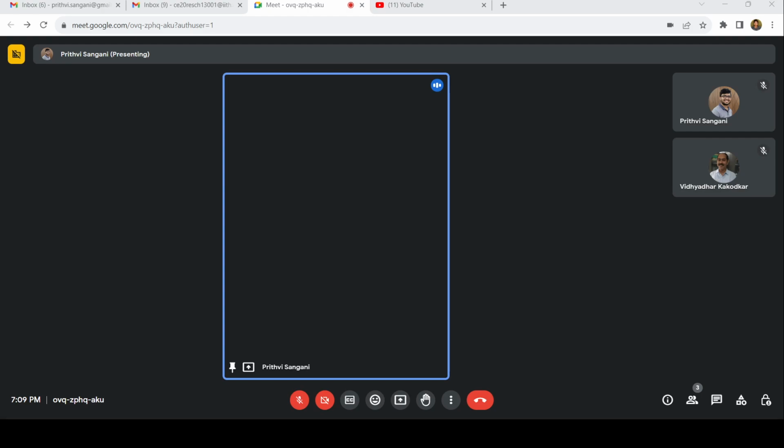So Fi is going to be 10 for AB, BC it's 10 root 2, CD is minus 10 compression, BD is minus 10 compression, DE is 0, and BE is going to be 0 because there is no force in it, right? We have assumed that we have removed the support, we have removed the member BE. So this is minus 10 root 2.